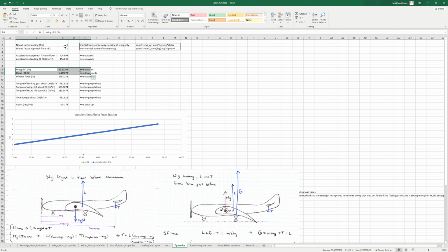we can estimate, like, let's say 4 Gs here for if we have some relatively thick tires. If we have very thin, like plastic tires, maybe we'd have to do more. Maybe we'd have to do 6 Gs. If we had suspension, like very plush landing gear, maybe we could even put 3 Gs, something like that. But for the example, that's what I've got here. So that's what these two tabs are doing together.